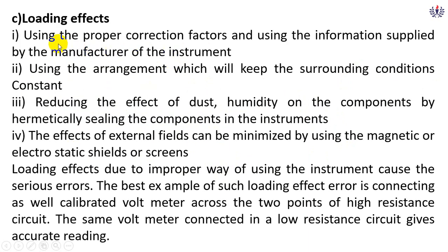Then loading effects. This is nothing but using the correction factors given by the manufacturer. If you are not using the correction factors, you will get the loading effect error. And use an arrangement which keeps the surrounding conditions constant.